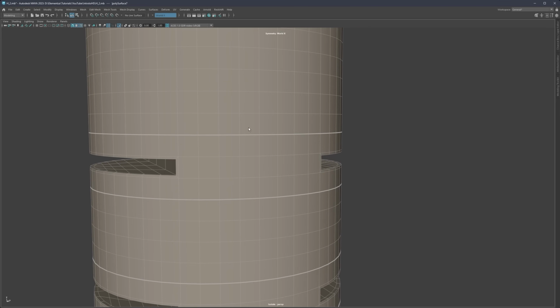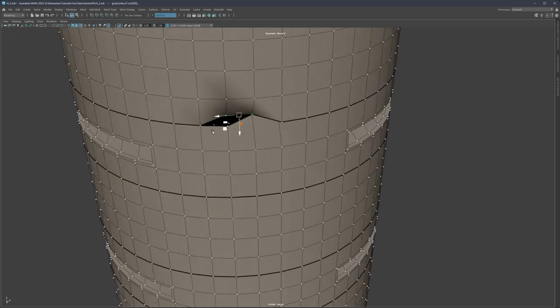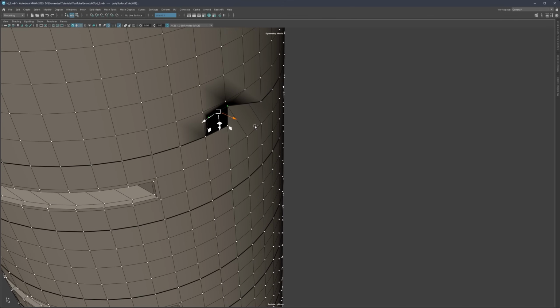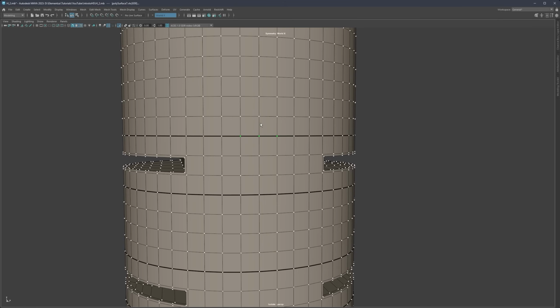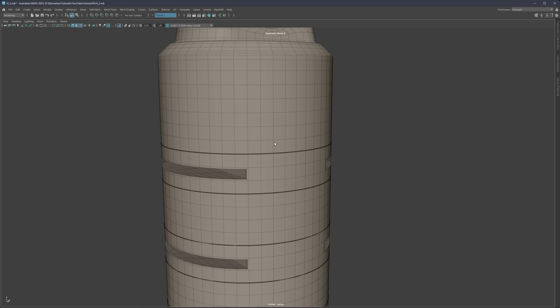Because when you subdivide this, or when you decide, let's say, to move a face, camera-based selection is on. I just want to show you this. You're going to see that these parts are not actually connected. So this thick line simply means that the parts are still open and that the edges are not connected.